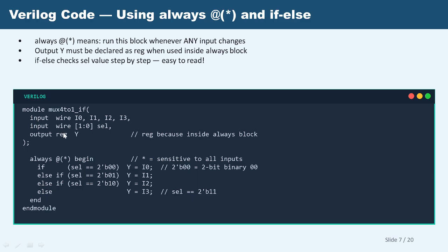And here we have the always @ begin block, right? What is it going to create? This is going to create a procedural block. So when you use always @(*), you need to use reg for output. For output you should always use reg. Just don't miss this reg while you are using an always begin block.